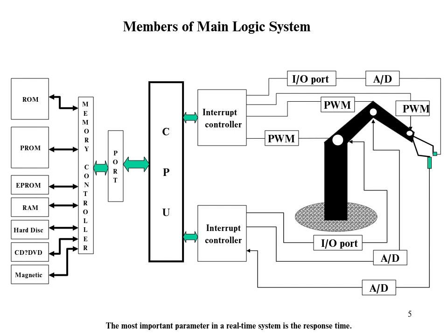Within the microcontroller we have the CPU, and outside, in this robotic example, we need PWM, pulse width modulator, in order to control the motor, for example an electrical motor, and an analog to digital converter, because we have analog signals. And obviously we need memory. On the left hand side, as you can see, ROM, EEPROM, PROM, RAM, hard disk, magnetic memory, those kinds of things we need for any kind of control implementation.